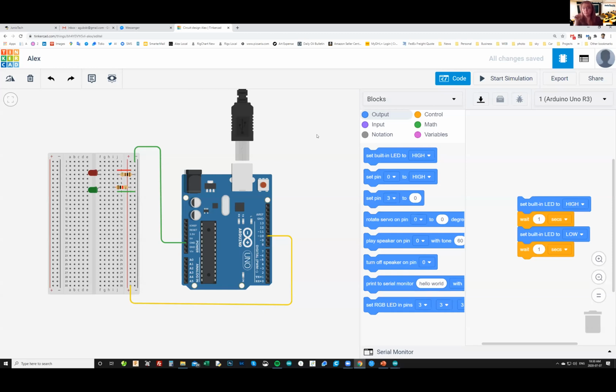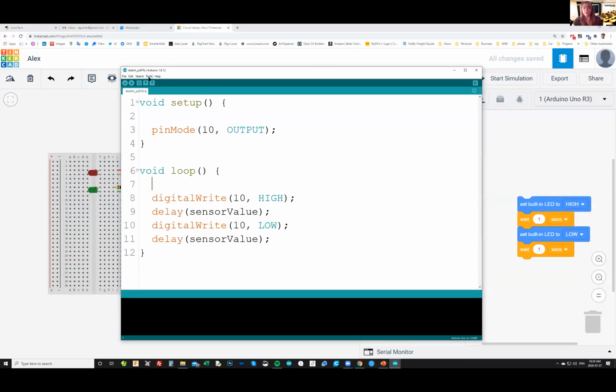And just one more trick I want to cover, because that's a mistake I see very often. People forget to check the port part. Alex, can you open the IDE please? There you go. Before you can push this to your Arduino, you want to make sure that your program communicates through the same port where your Arduino is connected. What does port mean? Those USB openings on your computer where you connect your Arduino device are called ports, right? So they need to connect to the correct port.